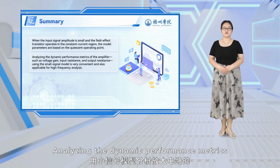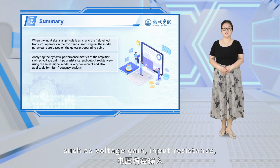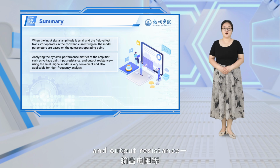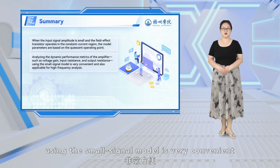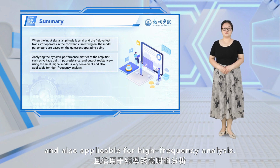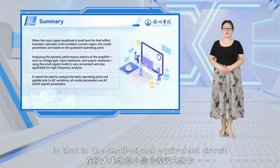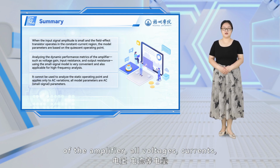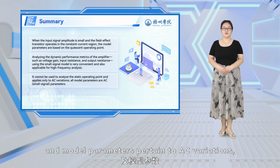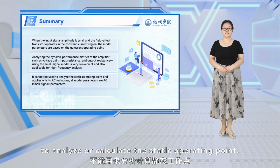point. Analyzing the dynamic performance metrics of the amplifier, such as voltage gain, input resistance, and output resistance, using the small signal model is very convenient and also applicable for high-frequency analysis. The drawback is that in the small signal equivalent circuit of the amplifier, all voltages, currents, and model parameters pertain to AC variations, and thus it cannot be used to analyze or calculate the static operating point.